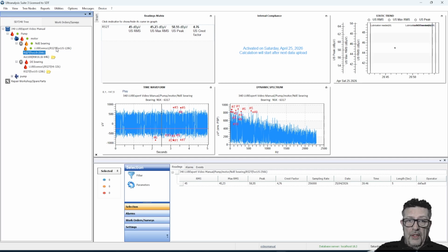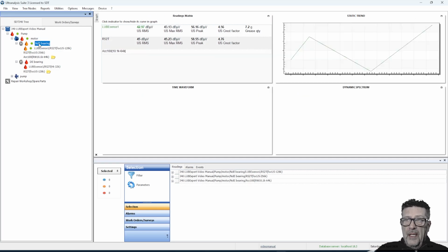If we need more data, if we do the lubrication in a low resolution, we can still set up the sensor like I did here in a higher resolution, and the same person, without even moving the sensor, will do the job immediately after lubrication. So this is what I mentioned before about the optimization. Now when we talk about each point, no drive-in bearing, we can have all the data here. Lubrication, condition monitoring, I can add vibration, I can add temperature, RPM, everything will be in one place.